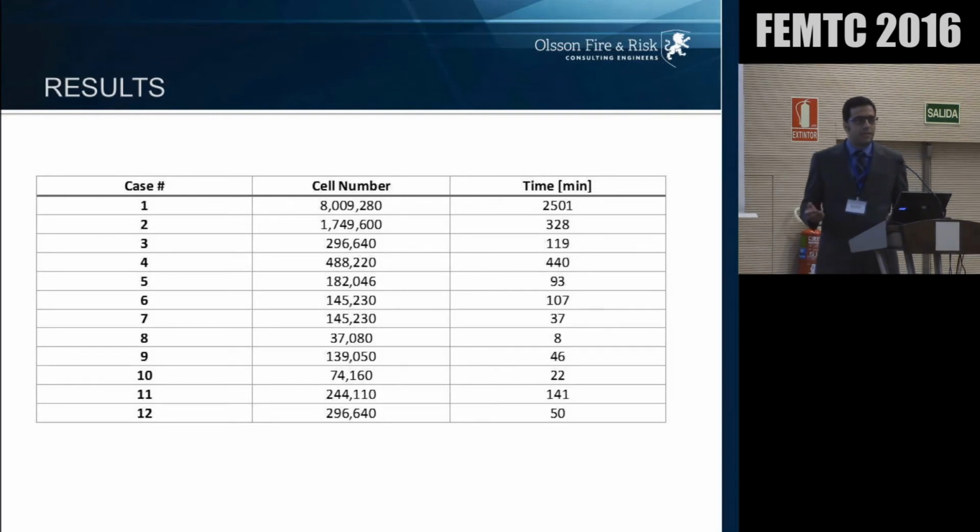Normally, when Fire Brigade asks for a simulation for JETFANs, we're looking for a minimum of 1,200 seconds. So, on normal car parks, medium or large size, you're talking about maybe 10 to 50 JETFANs. Imagine if you want to run that scale on your car park. It's a question, actually, which we need to ask ourselves: do we really need to go that accurate using